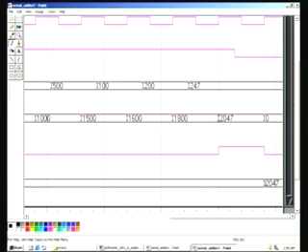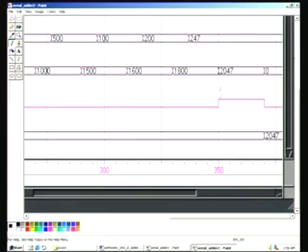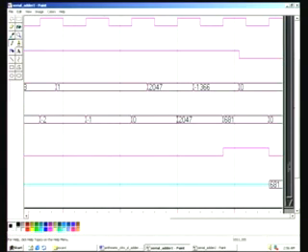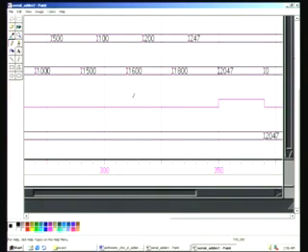You note that one. If you take this timing, it is coming at 350 nanosecond here, whereas in the first one what we have seen, this is corresponding to 170. So 350 minus 170 is 180, and each is 20 nanosecond. That means 9 clock cycles it has taken. So this proves that the serial ladder is 9 times slower when compared to the parallel ladder or concurrent ladder, which we will be seeing next. Thank you.